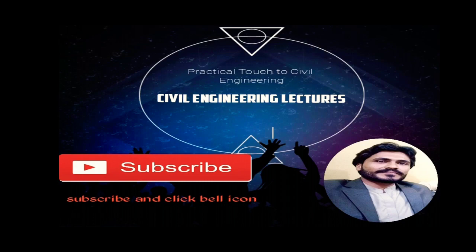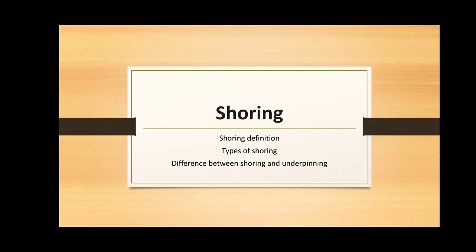Dear friends, in today's video, we are going to discuss shoring. First of all, we need to understand shoring. Shoring is actually the temporary support to a structure where foundations are to be repaired. It is used to prevent a structure from failure or collapse when a structure is damaged due to foundation settlement or other causes. Shoring is also used when adjacent foundations are treated.